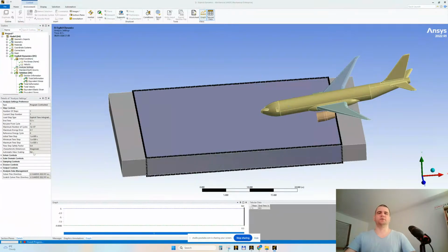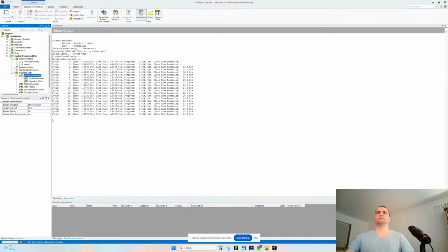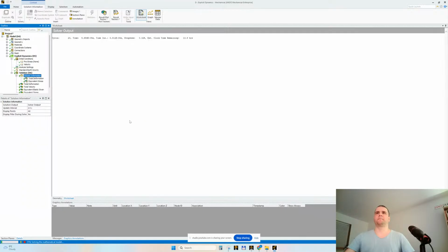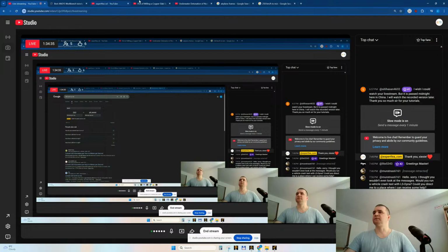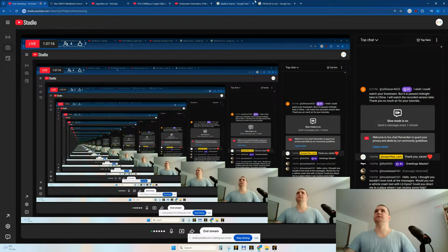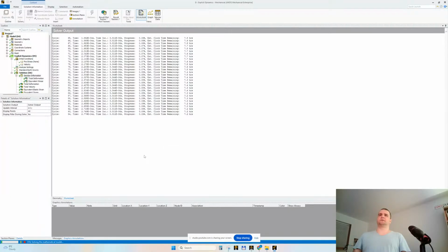Then we can edit the mass scaling. Then we can reduce the number of Eulerian cells to make a coarser, a less fine mesh on the Eulerian side for the water. How long will it take instead of 2.5 hours? I think maybe it will take the same. Let's look a little. I'm watching for questions. I'll write, okay, perfect. 7 hours.